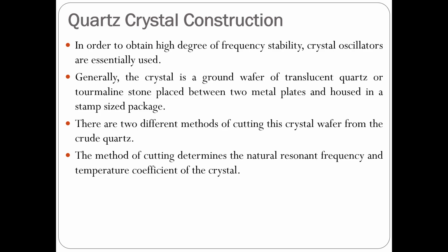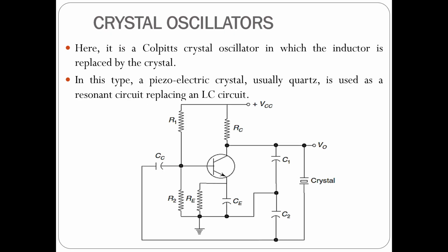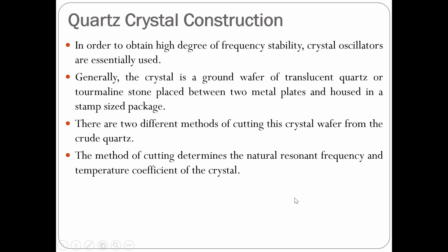Next one, crystal oscillator. In the crystal oscillator, the inductor is replaced by the crystal. So the piezoelectric crystal, usually quartz, is used as a resonant circuit replacing an LC circuit. So in place of C1 and C2, the crystal is used. So quartz crystal